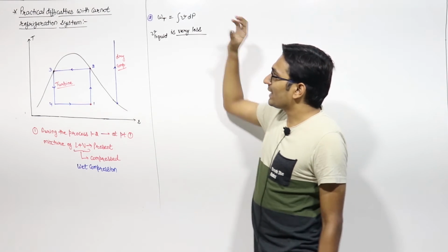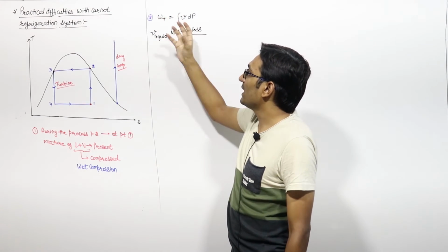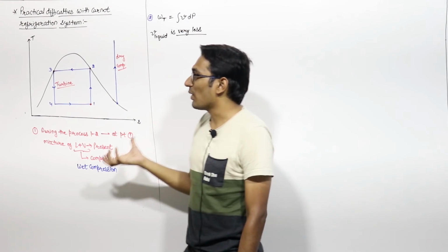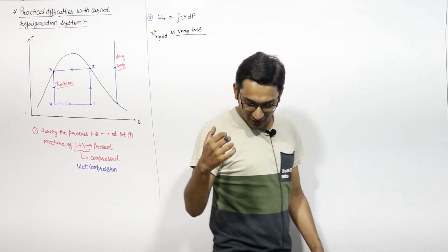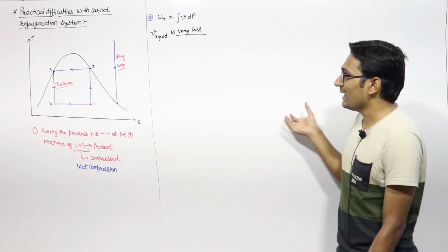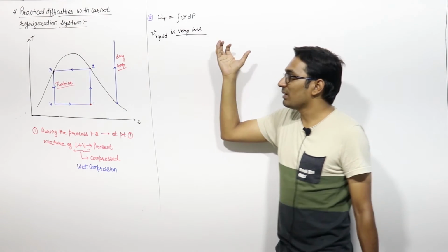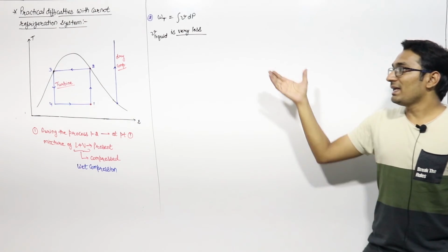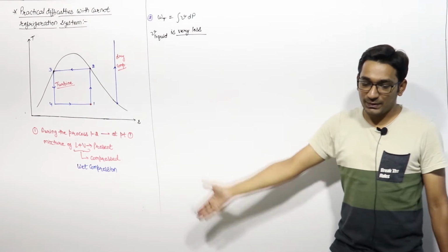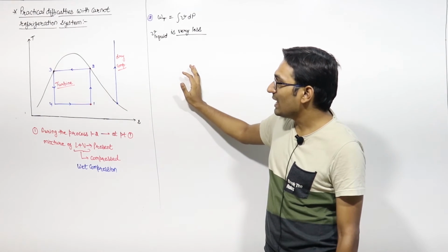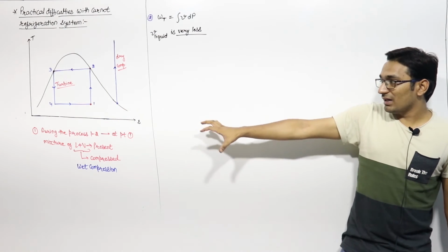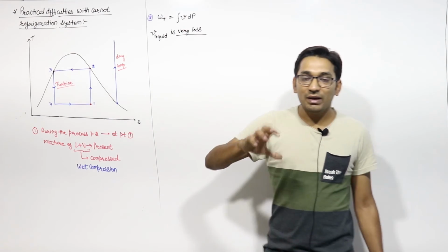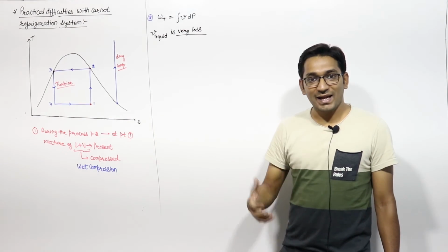So installing a turbine to get very less work is not practically feasible, because the turbine's cost itself is very high. If you are not getting enough work which can compensate for the compressor work WC, then there is no use of using this turbine as an adiabatic expander, right? So because of these practical limitations, we modified this Carnot cycle as per our need.